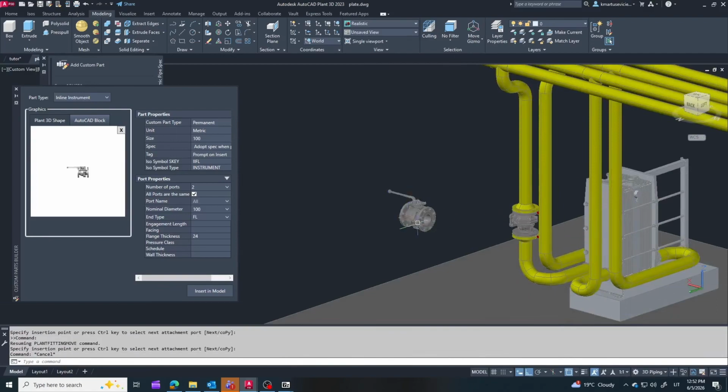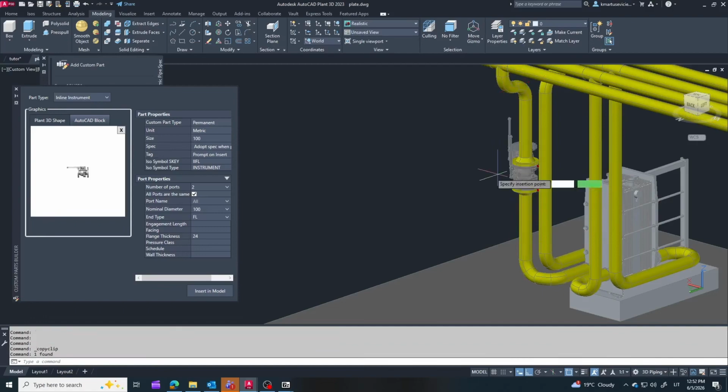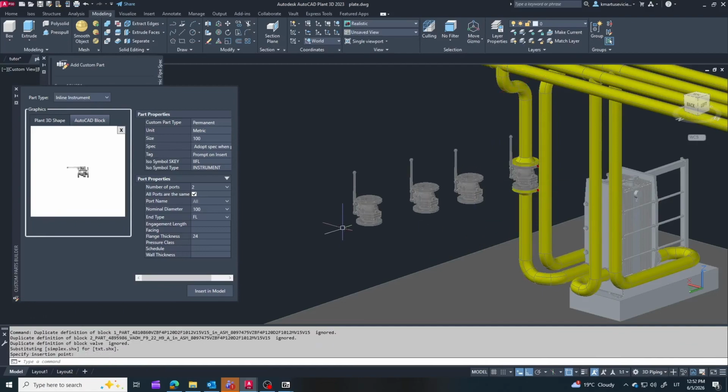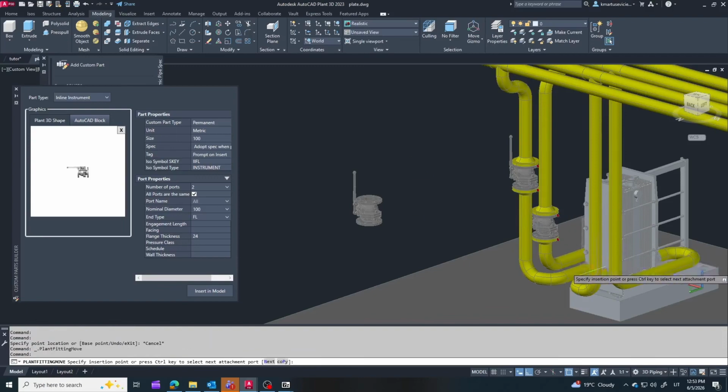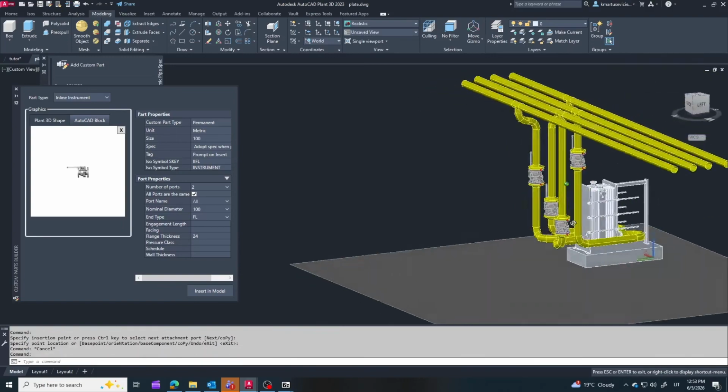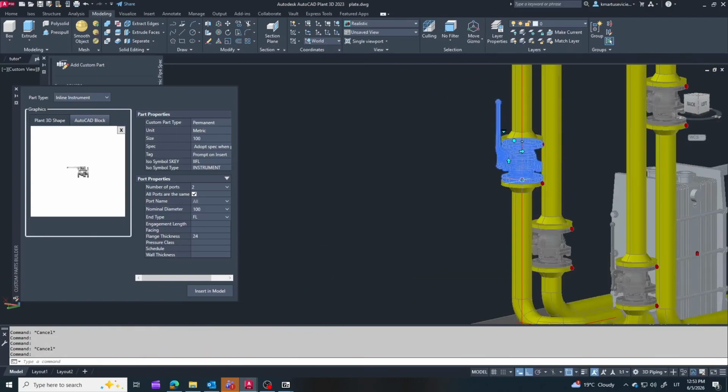Notice how I placed 2 of the valves lower down and the other 2 slightly higher up. This is a deliberate technique called staggering. By offsetting the valve positions, we prevent the wide flange assemblies and insulation jackets from crowding each other. It gives us maximum clearance between the lines and makes bolt tightening much easier on site.